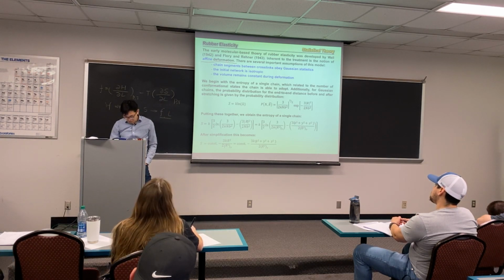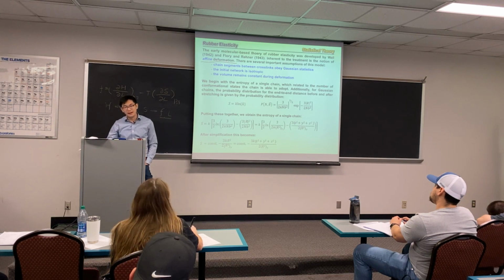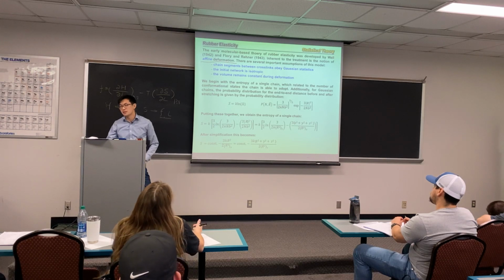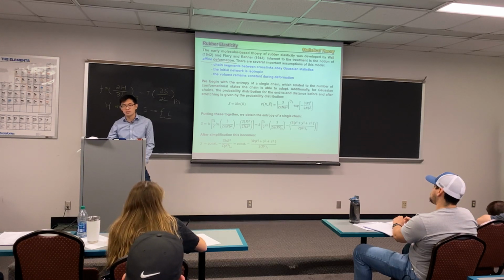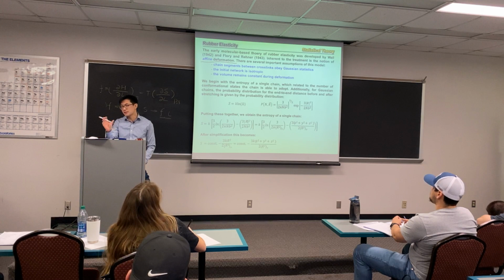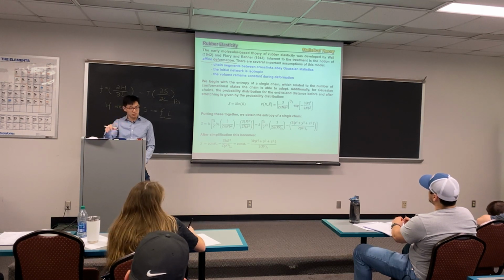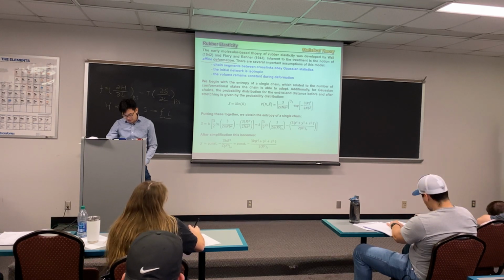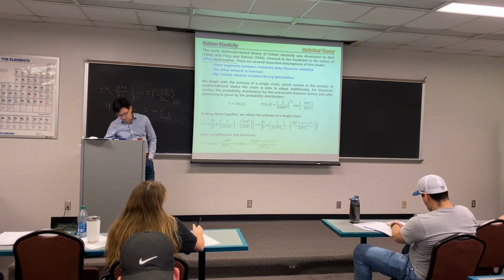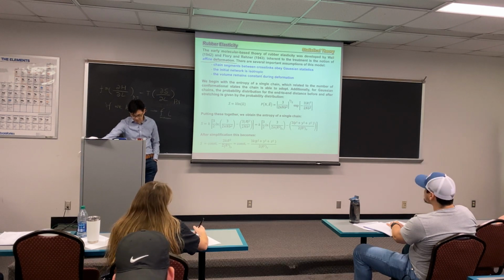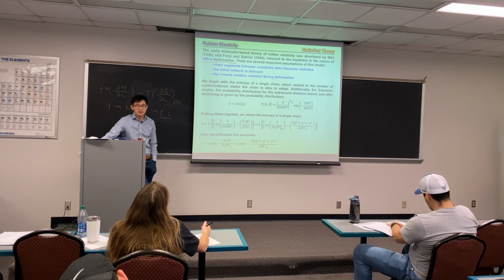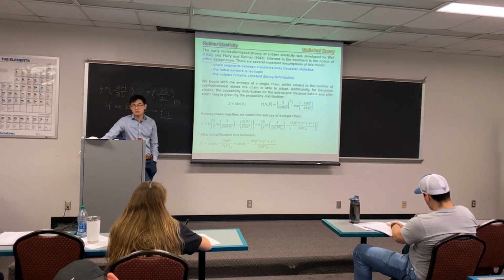The initial network is isotropic. You don't want any preferred orientation because otherwise it does not follow the Gaussian coil assumption. The Gaussian coil means it's isotropic in all directions. And the last, most important, is that volume remains constant during deformation. This is mostly true because for rubber bands or elastomers, the Poisson ratio for an ideal elastomer should be 0.5.